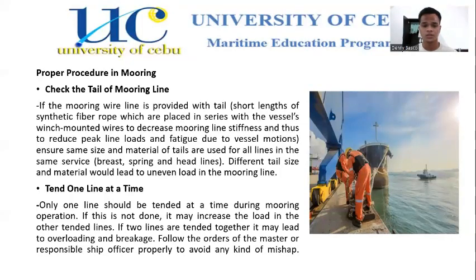Ensure the same size and material of tails are used for all lines in the same service. These are the breast, spring, and head lines. Different tail sizes and materials would lead to uneven load in the mooring lines.